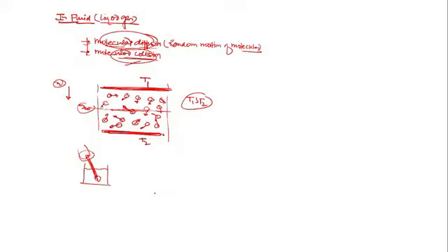So this loss of energy is from the inside of the room to the outside. That is because of conduction heat transfer through the wall, basically. So there are various examples of conduction. These heat transfer processes can be quantified in terms of an appropriate rate equation. So what is the rate equation for conduction heat transfer? That is given by Fourier's law.